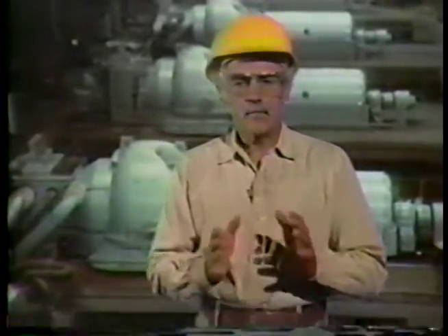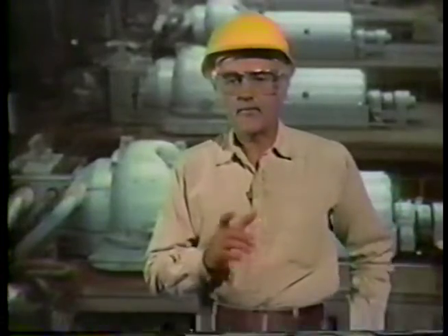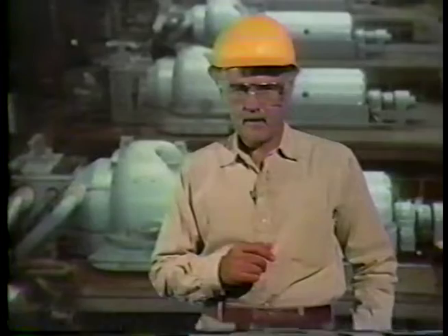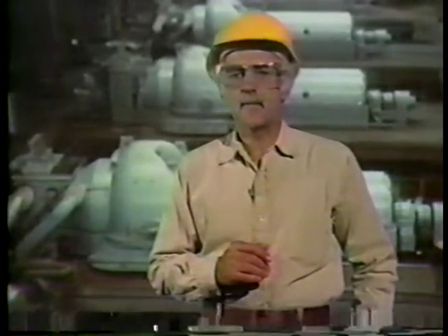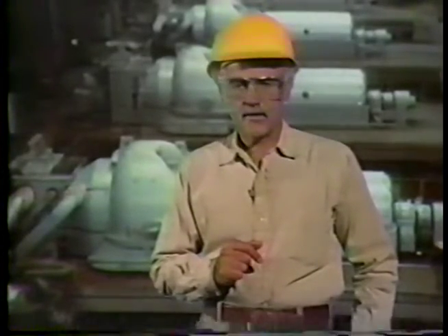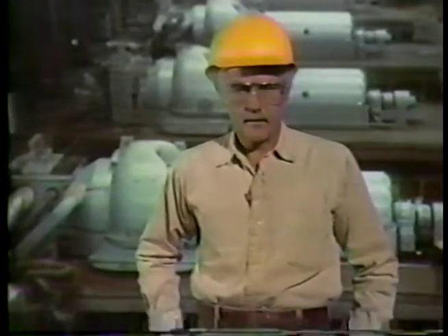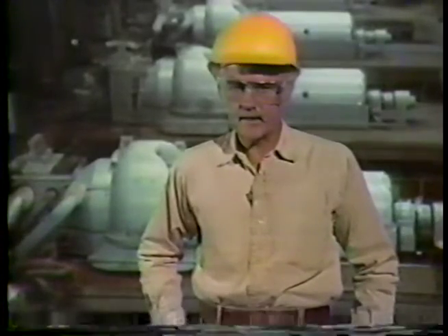One of the most important uses of oil in a turbine is for bearing lubrication. Bearing lubrication supports the turbine rotor, allowing it to rotate while preventing metal-to-metal contact between the stationary and moving parts. In addition, the lubricating oil carries away heat built up in the bearings. Lube oil is also used for hydraulic control systems in some turbines. Since lubrication of a turbine is so important, we need to see how the lubricating oil is supplied to the areas where it does its job.